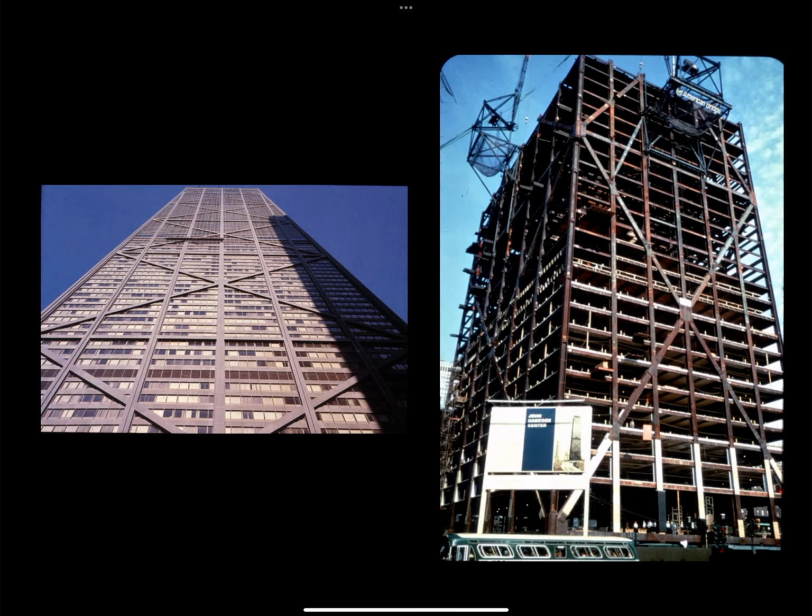So in the Hancock building in Chicago, you see the steel frame on the right, and you see it's painted that dark red to protect it from moisture. And then on the 3 stories at ground level, you can see the steel structure has been wrapped in a white blanket of material, a fire-rated material. So we can wrap it with a fire-rated blanket. That's another method. The most common method of fire protecting steel is spray-on protection.